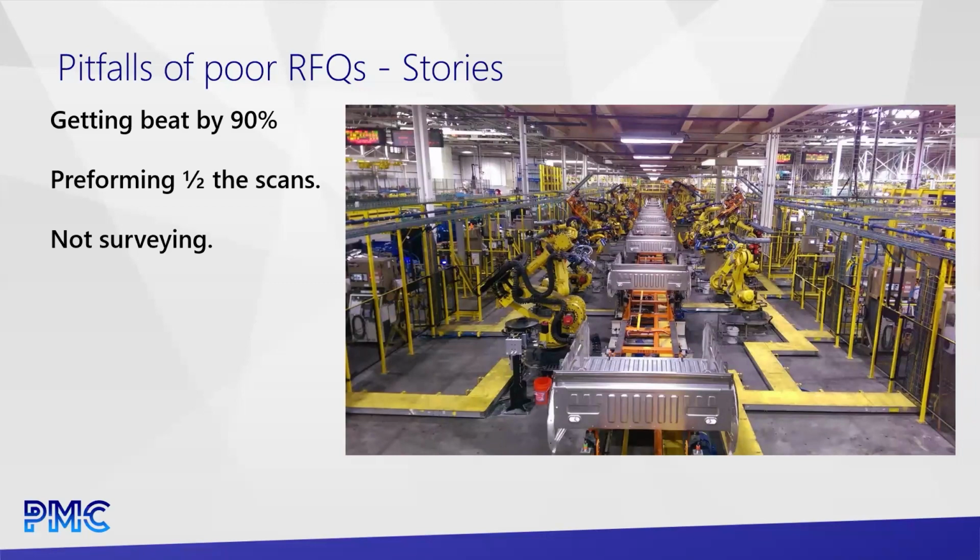The other thing that surveying locks down is level. And so again, we see this a lot in warehousing, any large volume spaces. The scanning equipment can compensate for level to a certain extent, right? In other words, when you run a scan, let's assume that the floor was perfectly level in the space. It's not, but let's assume it was. The scanner is going to hold that level pretty close. And especially depending on the type of scanner you use, it can be really close, but it's not great.